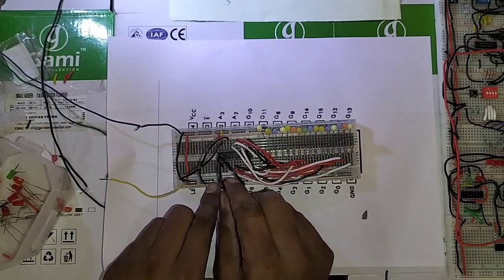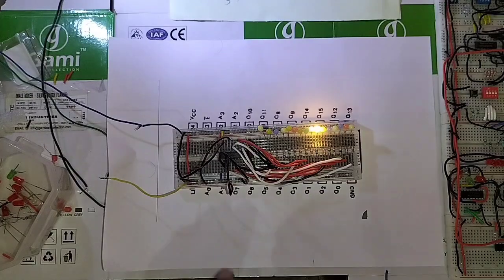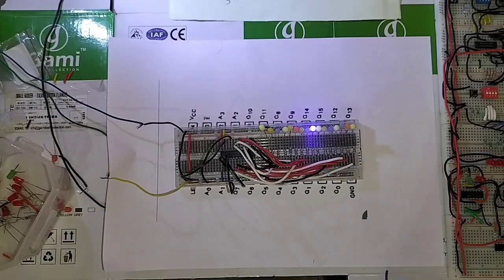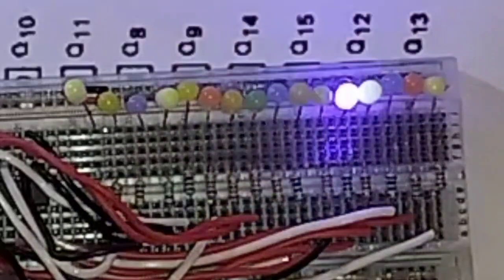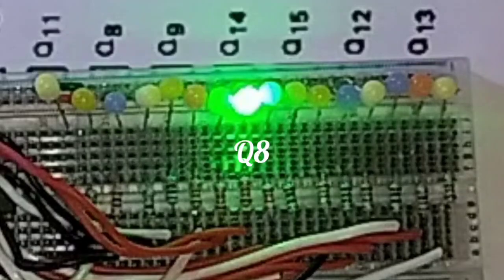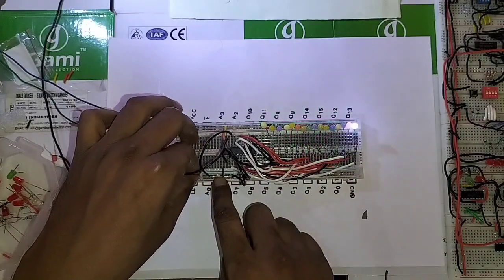The fetch cycle of the computer is independent of instructions. That is, it is not dependent upon any instructions. The counter out, memory address register in, and RAM out, instruction register in, and counter enable is our fetch cycle. Here we have 4 steps at maximum: 00, 01, 10, and 11. Steps 00 and 01 are nothing but the fetch cycle. Steps 10 and 11 are connected with the instructions of our 4-bit breadboard computer.